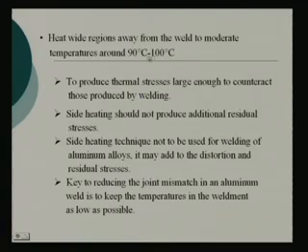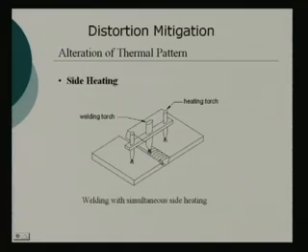But these values, 90 to 100, are not very sacrosanct. All these will depend, because the whole idea is altering the thermal pattern. So, it is not recommended that you just start side heating. Nothing is mentioned about what the distance between them should be. All that will depend. If I heat up to 100 degrees centigrade, then probably this much distance. If I heat up to 400 degrees centigrade, probably I will have to increase the distance. I have to see which one gives me the best effect.